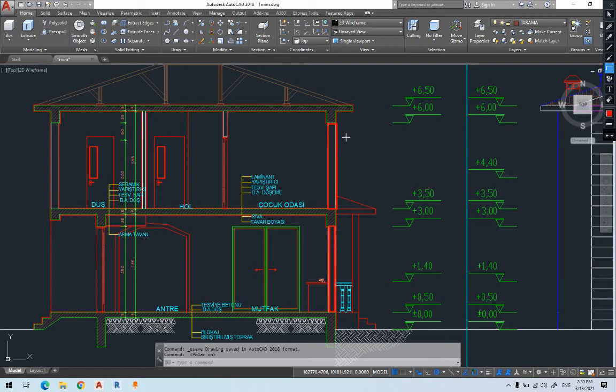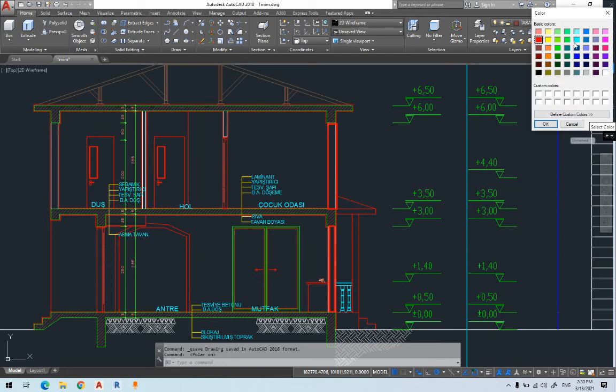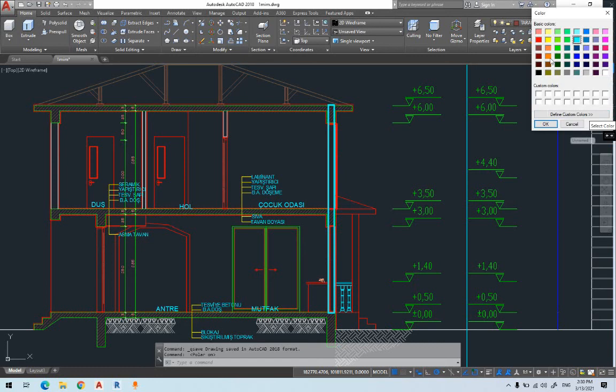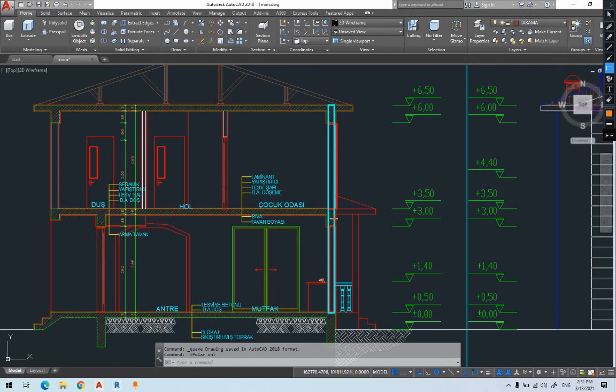Well, in Revit, when we're placing the column, it's okay to place the column overall. It's okay to place the column from the bottom, let's say from the top of the footing till the top. Now the reason, you will understand it later. When we place the beam, then Revit will replace this part with the beam. For example, when we place a beam and slab, Revit will take care of this extra material. So this part will be the beam and this will be the slab. So Revit will take care of this one.